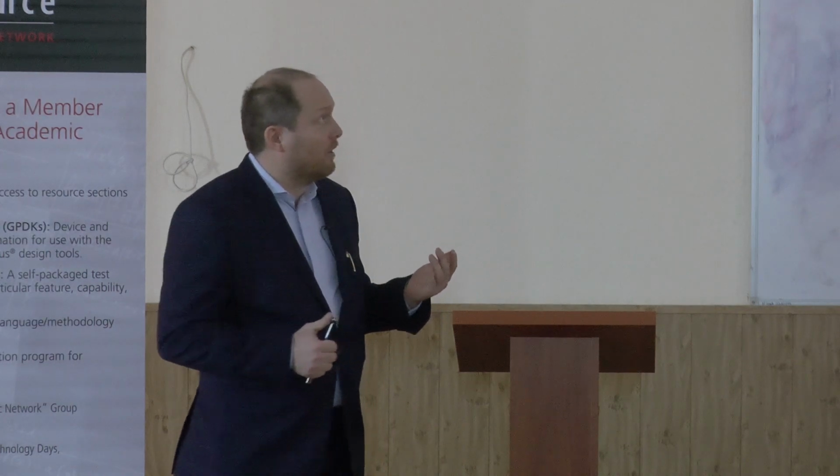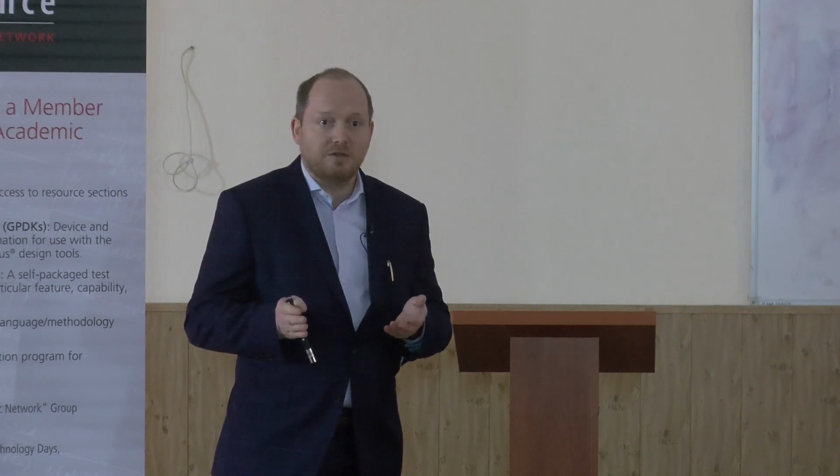And now if we look at a modern SoC, we see that more than 90% of the content of an SoC is memory. So therefore, Moore's law is not that important, because the amount of logic is decreasing in an SoC, but the amount of memory is increasing. And for memory, this learning curve is still valid. Okay, next slide.